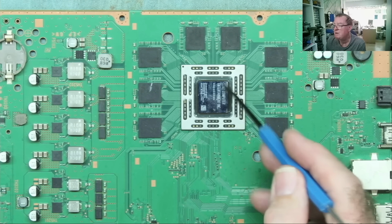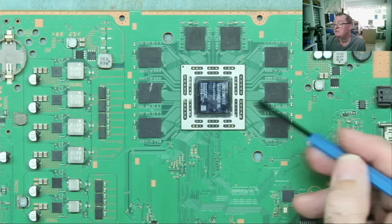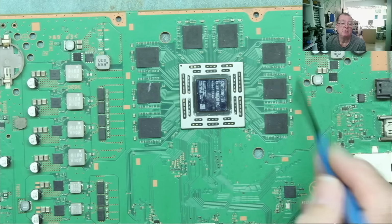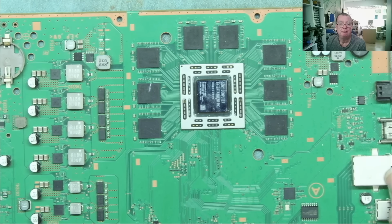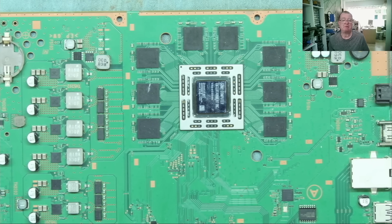You can't actually remove the die and replace the bumps, by the way. That at the moment, as far as I know, is not possible. So you can't actually repair those type of chips. Reballing, by the way, is taking the chip off, cleaning all the old solder balls off, putting fresh balls on with a template, and then resoldering the whole thing back on the board. That is reballing. So that's the difference between the three, if you wondered. Anything else is just messing around with a hairdryer or a hot air gun.